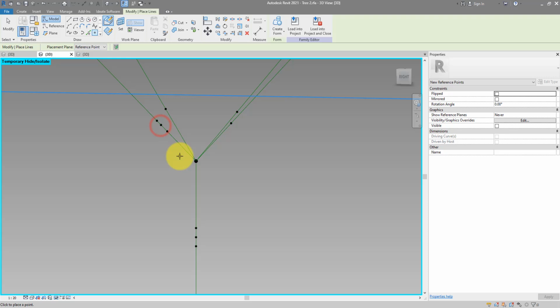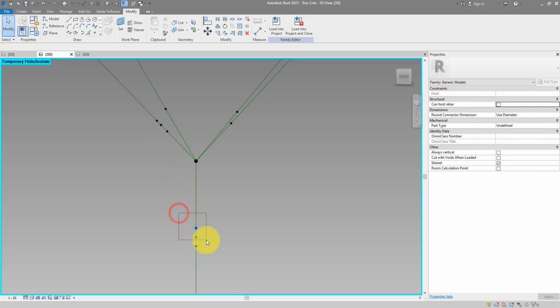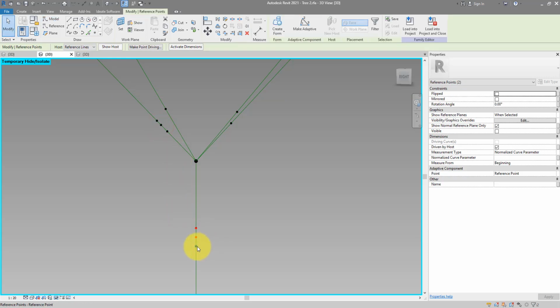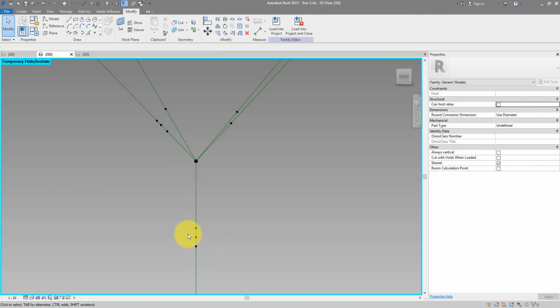3, 4. The trick is to place new points closer to the existing points, because here we are just having more points to keep the starting and ending segments of this connector element straight. In the middle it should be free to make this nice curve. And because I love parameters so much, let's put them in here as well. I can now select these 2 points.